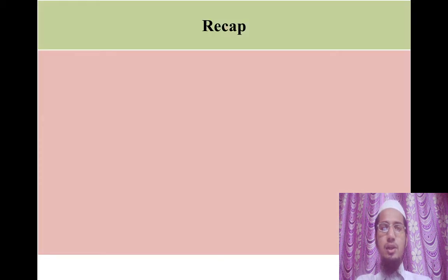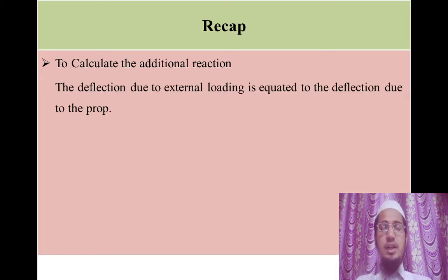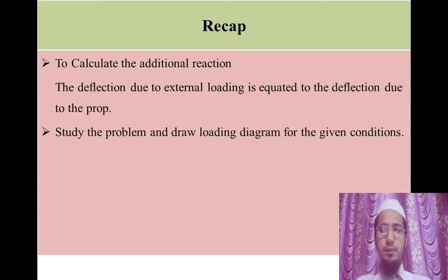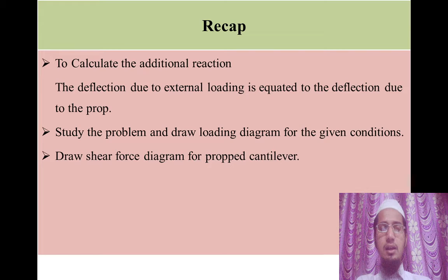Let's first recap what we have learned in previous sessions. In the case of a propped cantilever, to calculate the additional reaction, the deflection due to external loading is equated to the deflection due to the prop. We also studied the problems and were able to draw the loading diagram for the given conditions of the numerical, and also draw shear force and bending moment diagrams for a propped cantilever.